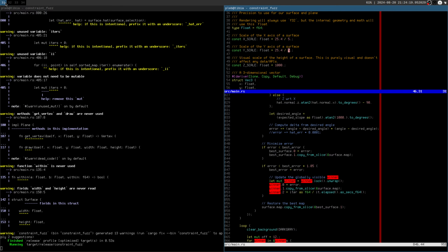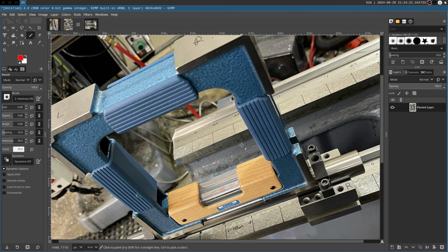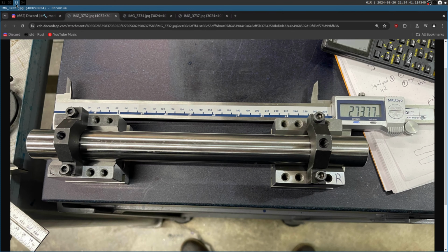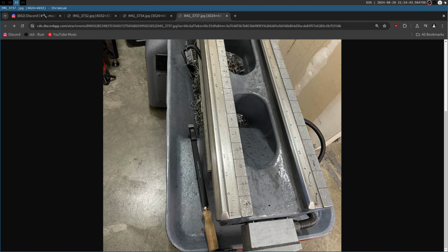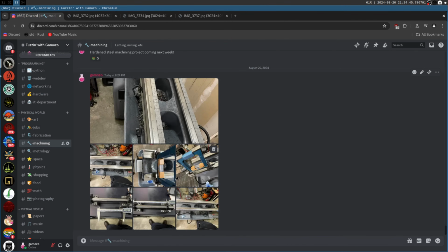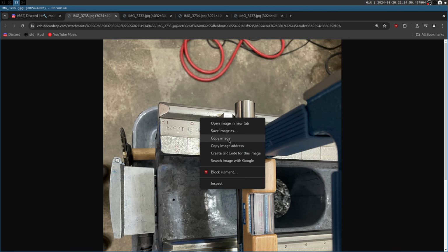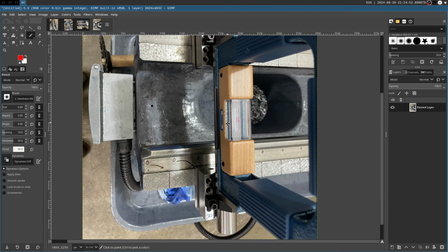And then there's one other measurement that we take. And the reason for taking these measurements is that they're not linking the two beds together, right? So these two beds could both be flat, but they could be in a completely different plane. They could be angled away from each other. All sorts of issues, right? So now, what I also do is I have another pass where I go horizontally across the two, which is the whole point of the dumbbell setup compared to the other setup.